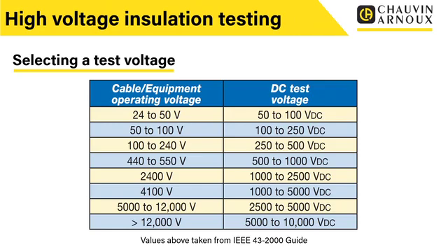So you can see on here, for typical circuits, our 230 volt main circuits for example, we would generally test somewhere between 250 and 500 volts, and a 500 volt insulation resistance test, as we talked about last time, is very common. But as the circuits start to go up, that's where we need to start using the higher voltages to actually get some information.